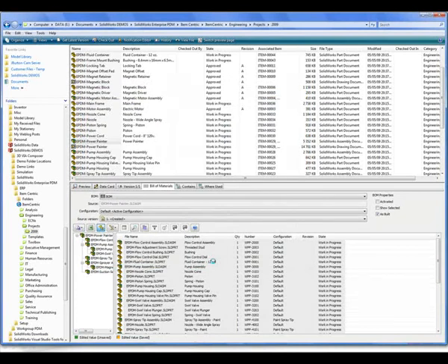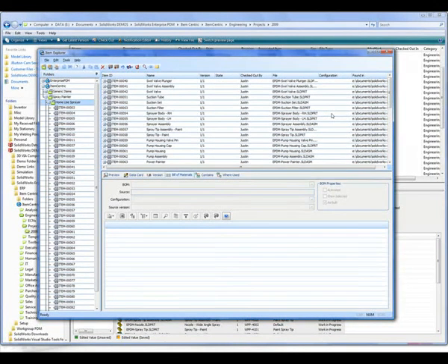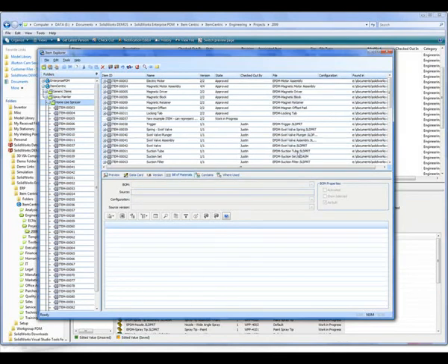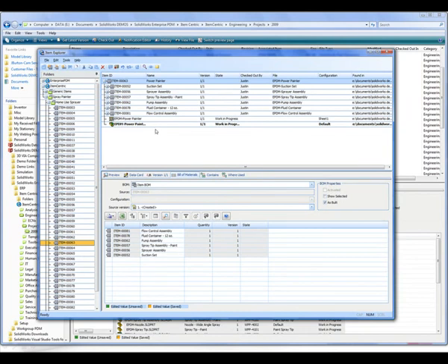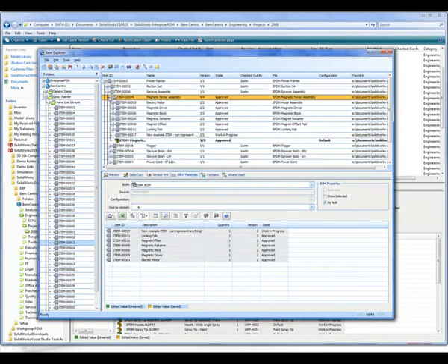Within the File Explorer, we are straight away shown which items are associated to the particular CAD files, making it very easy for anybody working on a design to see which components already have items. Back in the item master, and with the item numbers generated for the paint sprayer, we can now build our complete product BOM. As you would expect to see, to start with, the items are ordered in the same way as the CAD bill of materials, but any changes made, such as the new item we created, are also maintained within those sub-item levels.